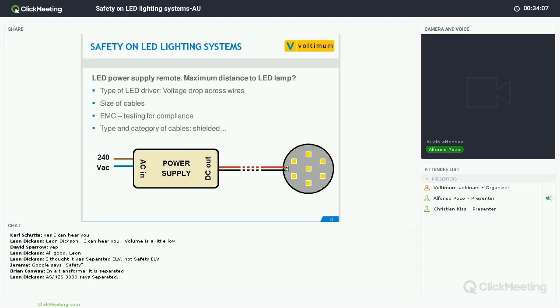This is the key point here. LED luminaires must comply with EMC standards and ensure any interference introduced in the surrounding environment remains below established limits. Usually lead wires in and out of the LED drivers are the most troublesome as they can behave as antennas emitting radio frequency noise.